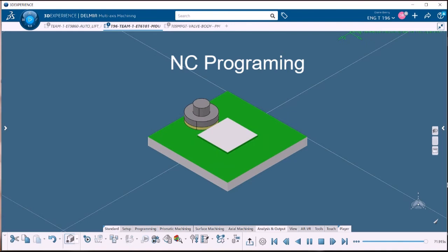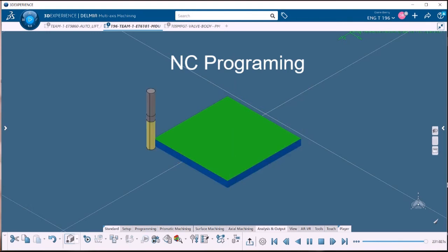It took 2 layers or 2 passes to remove all the upper material. Next, a tool change and a periphery cut to mill down the outer edges to get it down to full size. Then, we pop some holes in it so we can run some bolts through it and mount the part.